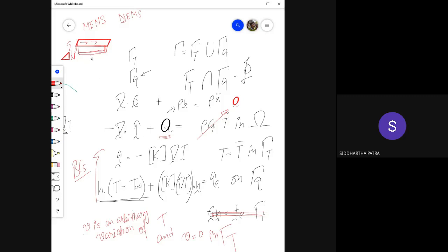Okay, but as you can see, this portion is narrow and this portion is wide, which means the electric current could be different in the two regions. Okay, because net electric current could be the same, but the density of electric current would be higher somewhere and lower somewhere, which would mean that some portions will have higher heat generation per unit area compared to the other. That means here you'd see more heat generation per unit area or per unit volume compared to this area, which